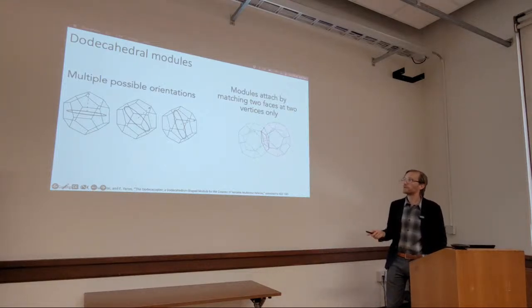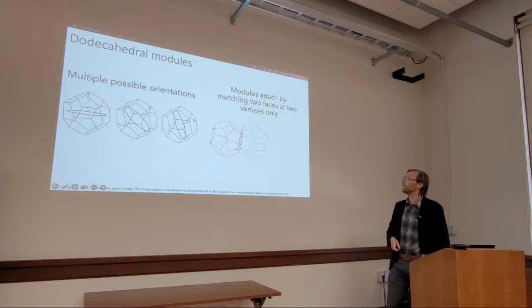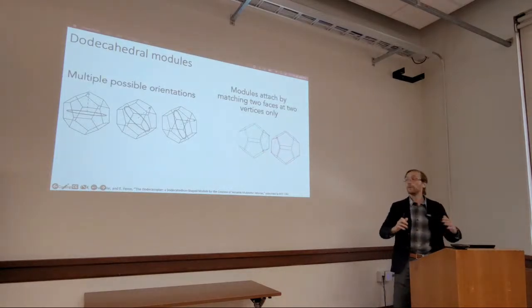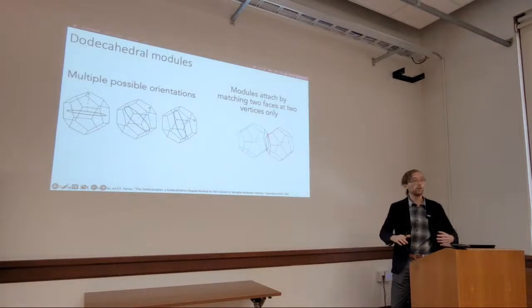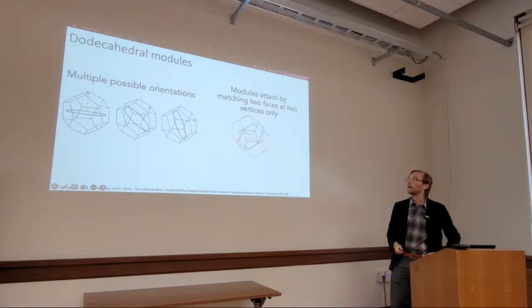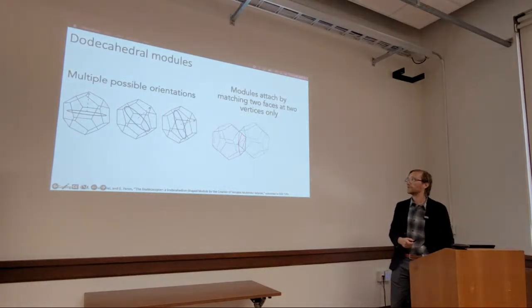The shape is that of a regular dodecahedron. It's just one of the 5 convex regular polyhedra. And the idea is that because of the symmetries of the dodecahedron, we can change the orientations of the propeller in a rigid vehicle. So it's when the vehicle is assembled that the orientation of the propeller is decided. But there are more possibilities, therefore allowing 6 degrees of freedom vehicles.